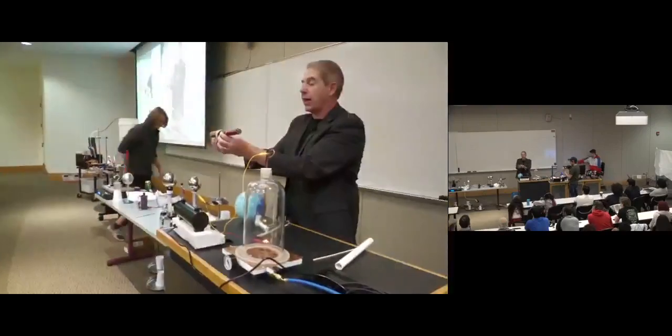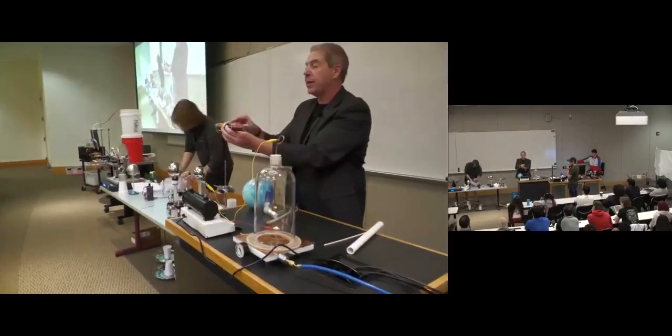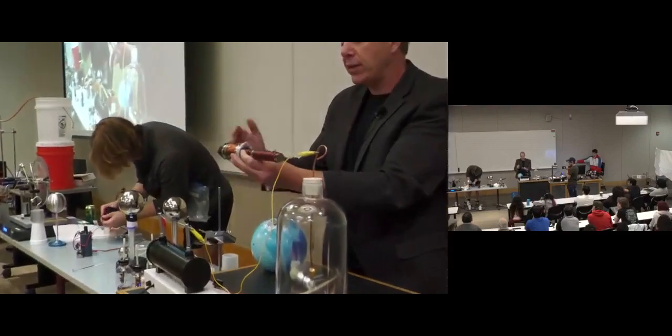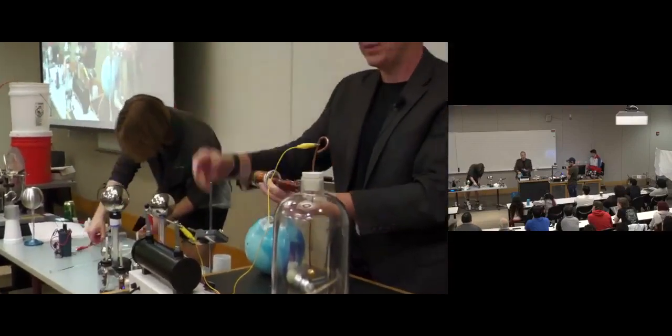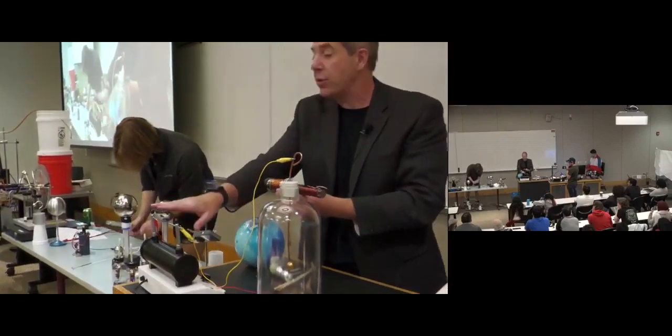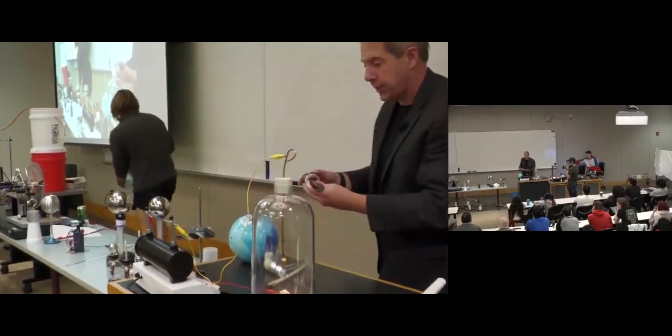So what it is inside of here, it's got a primary that we're going to put current through, and then this secondary on top. There's actually 2 of them connected in series, has thousands and thousands of turns, and when it disconnects, there's a transistor that connects and disconnects the current. It's going to go to 5, 10, 20, 30,000 volts across these.